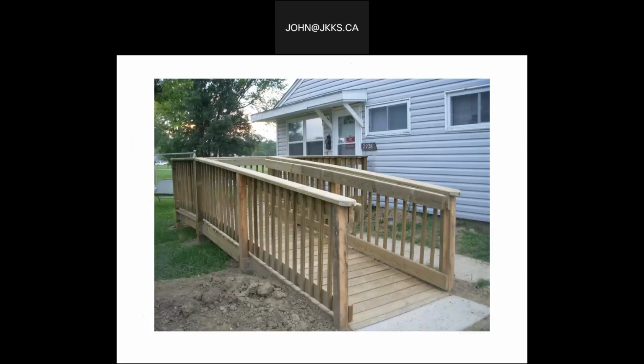Okay, let's get back to this particular image. When I look at it, you see a nice level concrete pad at the base of this particular ramp. We see the main structural posts seem to be well secured and appear to have structural support into the ground. The framing looks really in good condition. The actual build structure looks pretty good.